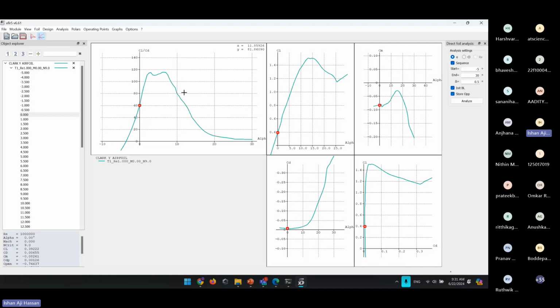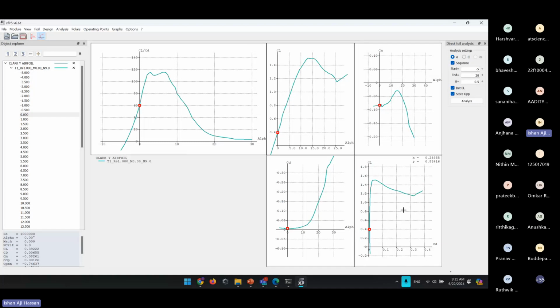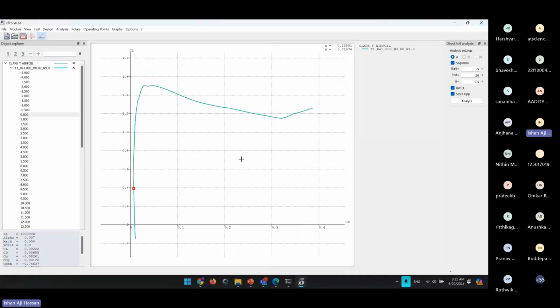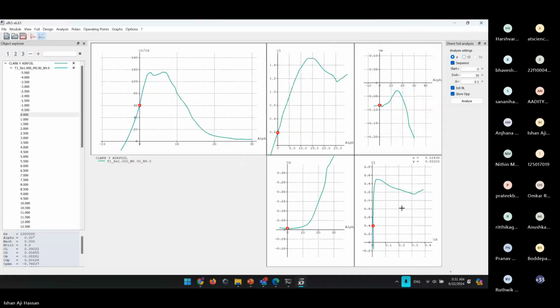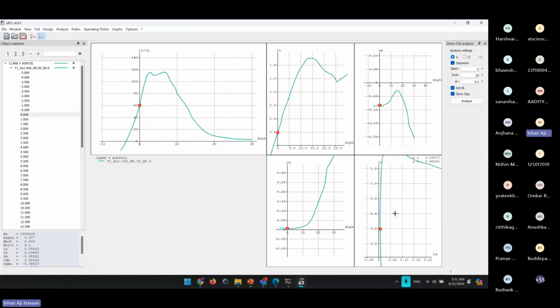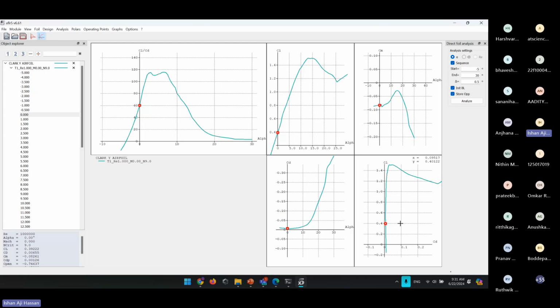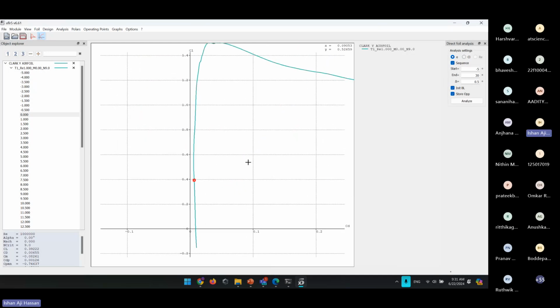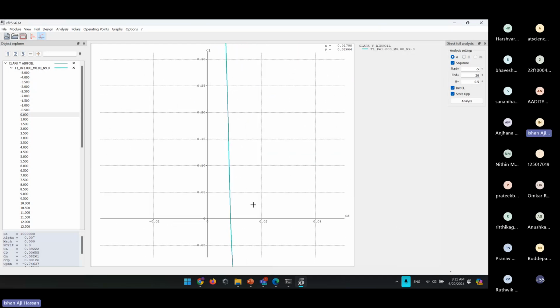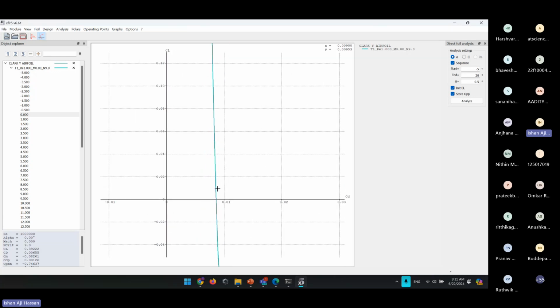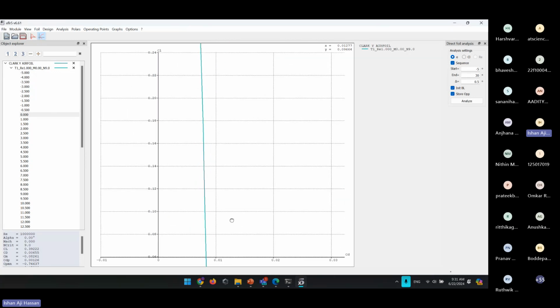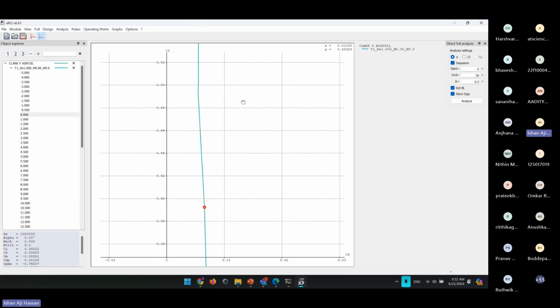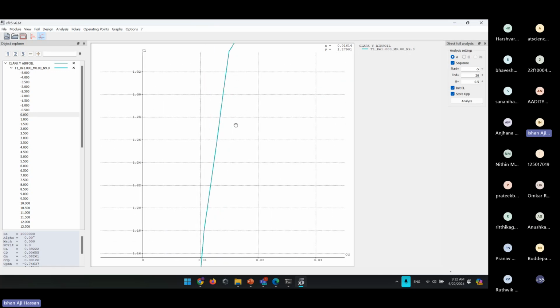So yeah, that's almost all the graphs. There is this CL by CD graph as well, which is not as important. I haven't really seen too much about this, but we can just quickly go over this as well. If you have noticed, this sharp increase here essentially is stating that, if you zoom in enough, you can see that this entire region is almost lying in the neighborhood of CD equals 0.01. So there's such a huge range of CL for the neighborhood that is close to CD equals 0.01.